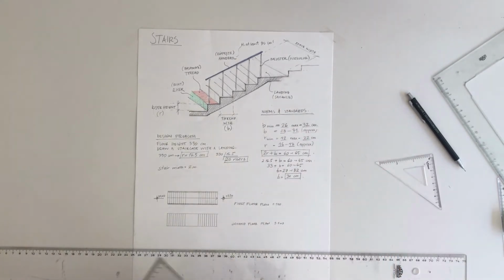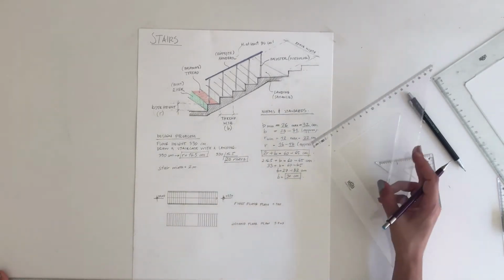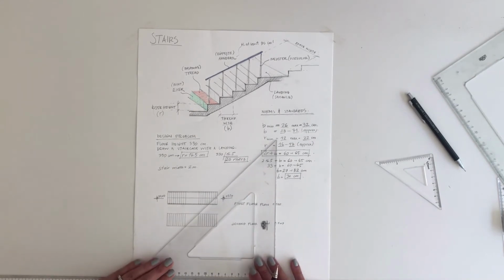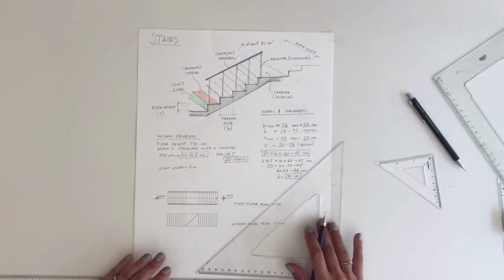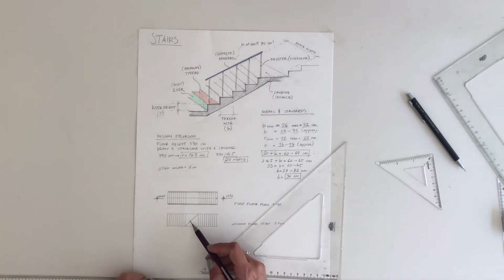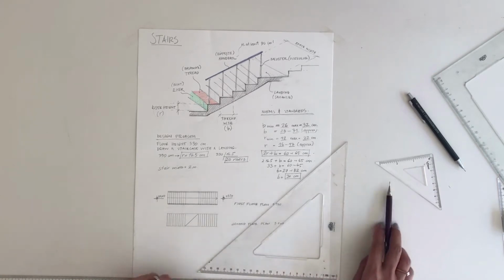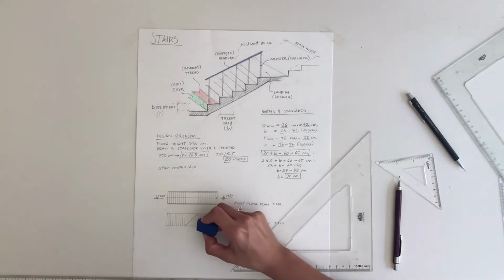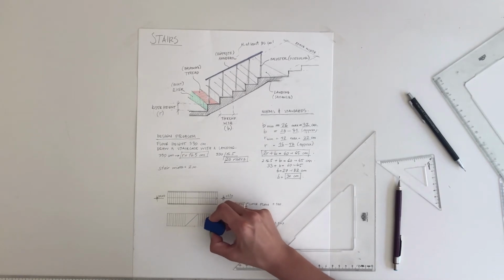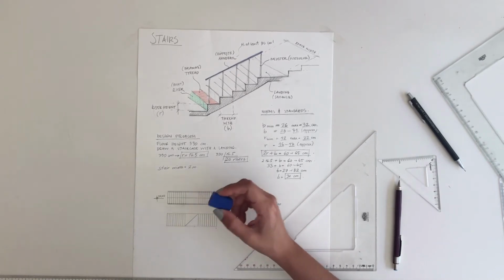Why? Because in the ground floor plan I cannot see the removed part of the plan. From somewhere here, for example in the middle of the staircase, I cannot see these upper parts. As these upper parts are removed from our view, I should show the parts with dashed lines.